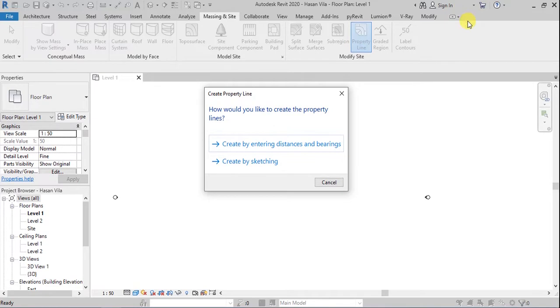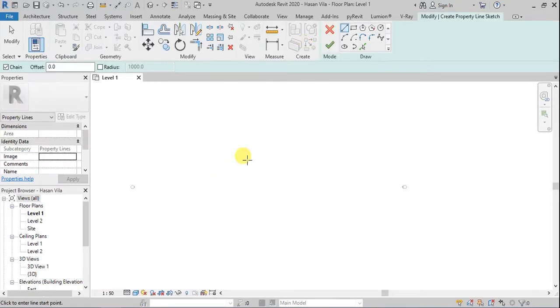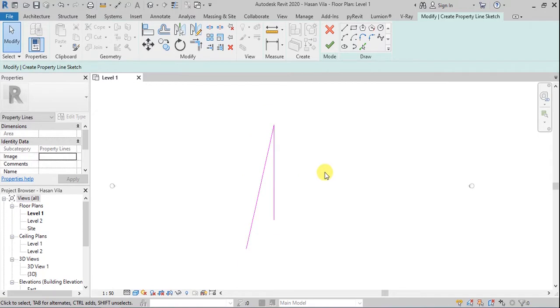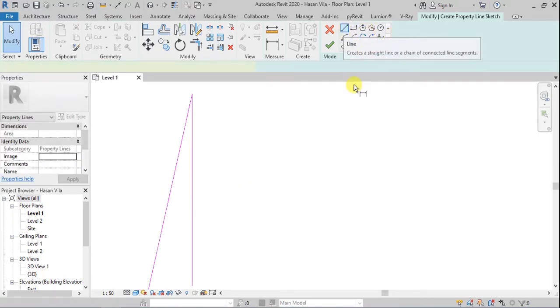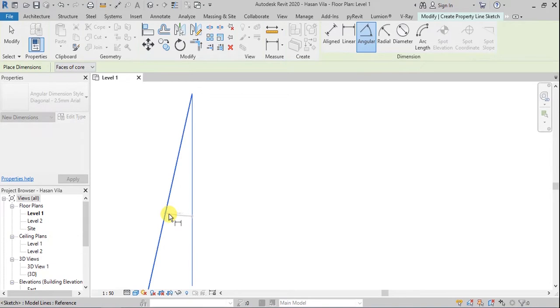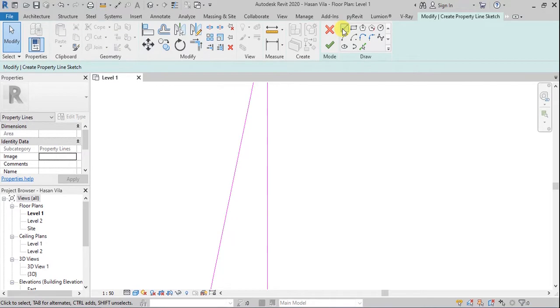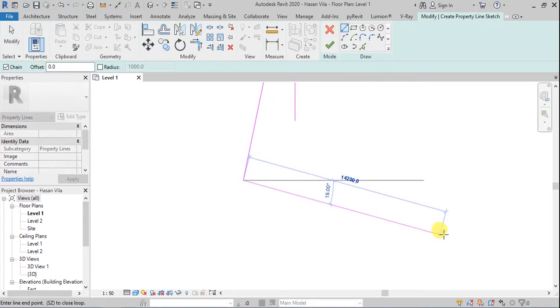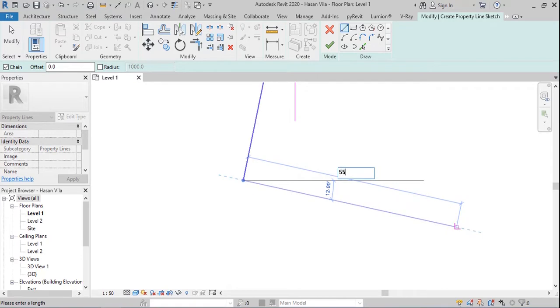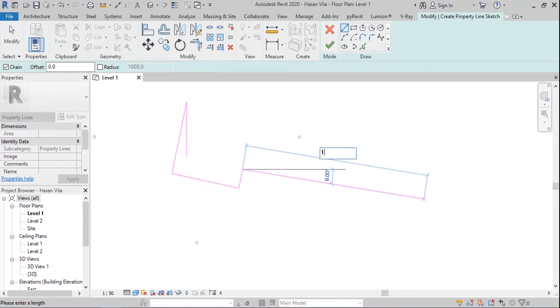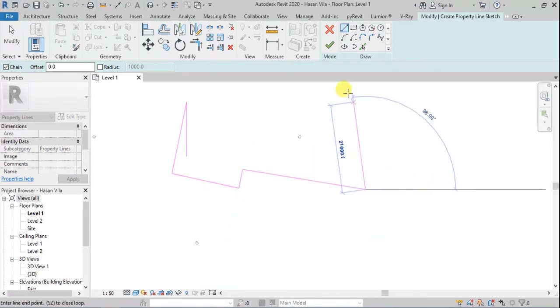So let's start. In Revit, my second site, property line, draw a straight line, angular line of 57 feet. Okay, DI for dimension, angular dimension. I need 12 degrees or 13 degrees, pick the line, make it 12 degrees. Okay, perfect, delete it. Now pick the line and go right side to a 12 degree angle, 55 feet. Okay, go upward 15 feet and rightward to 100 feet. Then again upward 60 feet.